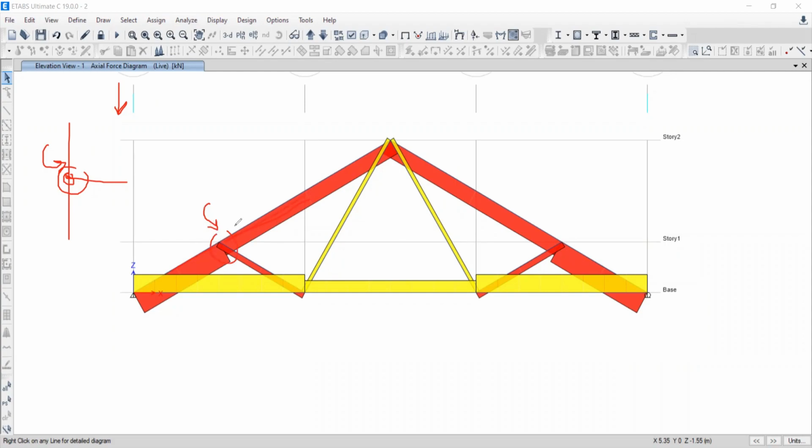Yes sir. Okay, that's why the ETABS software is showing the lesser result and your manual calculation is showing a little bit more result. That is what is right. In the manual approach, we are considering this joint as a pinned connection. Pin connection means it will not carry movement; whatever load you applied, it will make it axial and transfer it. You must have calculated it: an angle is formed, with sine of the angle we used to transfer the load. Do you remember or not?